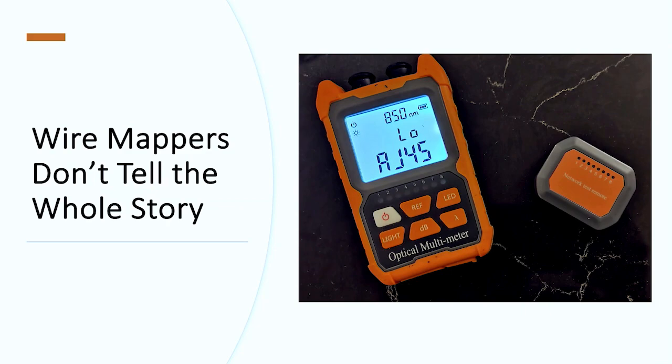We need to be testing that cable when it's installed to make sure that it meets the requirements of what we need, so that when we go turn on those APs, they're not flapping off and on and off and on because they don't have enough power.